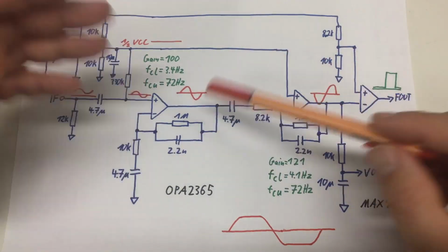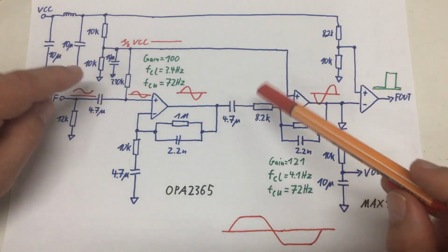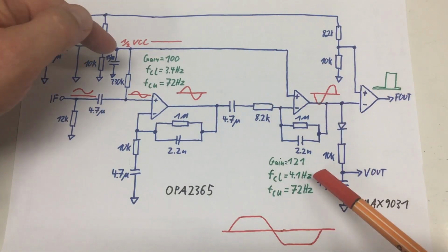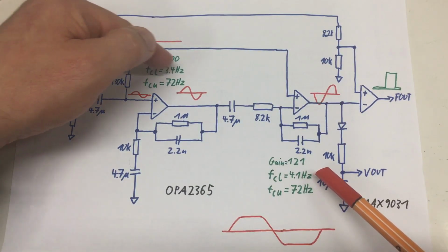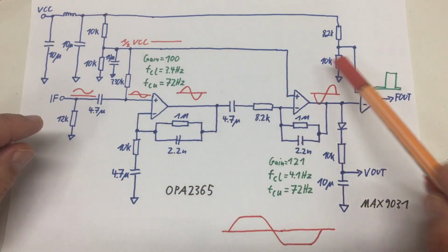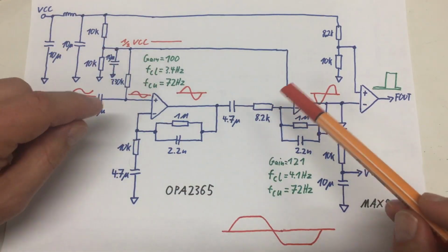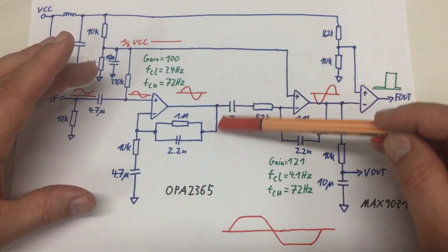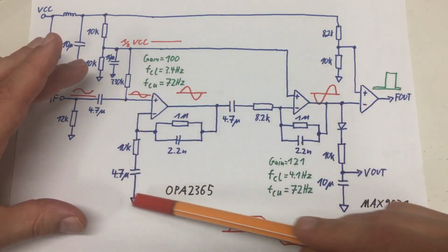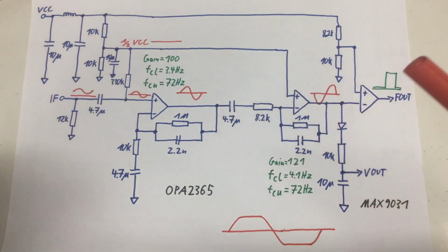One remark regarding the explanation of that circuit on Limpkin's website. There it states that the difference between the lower cutoff frequencies of the first bandpass filter and the second bandpass filter is intentional to eliminate any DC component that would remain after the first bandpass filter.